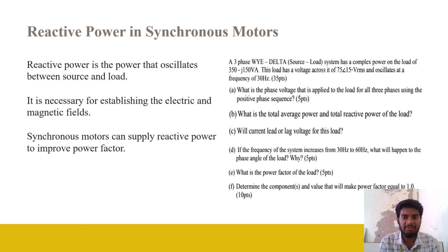And coming to reactive power in a synchronous motor, how does it relate? Well, reactive power is the power that oscillates between source and load. That means it oscillates, it could be like an AC type signal. It is very necessary for establishing the electric and magnetic fields. A synchronous motor can supply reactive power to improve the power factor.